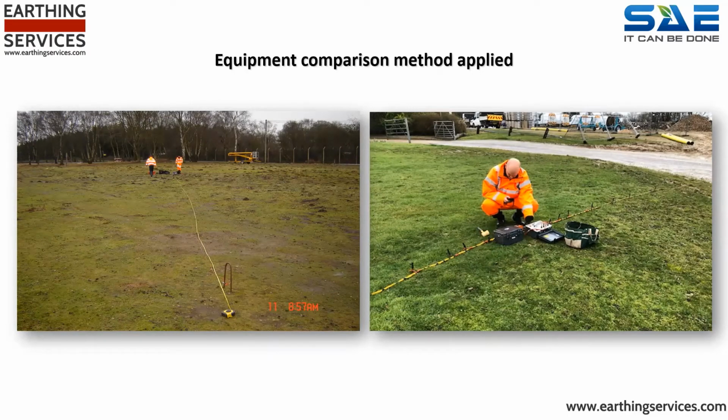The equipment that you can access, buy or make will determine the process adopted on site. The photograph on the left demonstrates engineers using 4 test cable reels and 4 test probes, being earth rods, which reference 2 measuring tapes to verify the distance between the probes. The engineers will likely determine the furthest current probe distance required, install the current probes at that distance from the central point, and then install the potential probes at their respective distance.